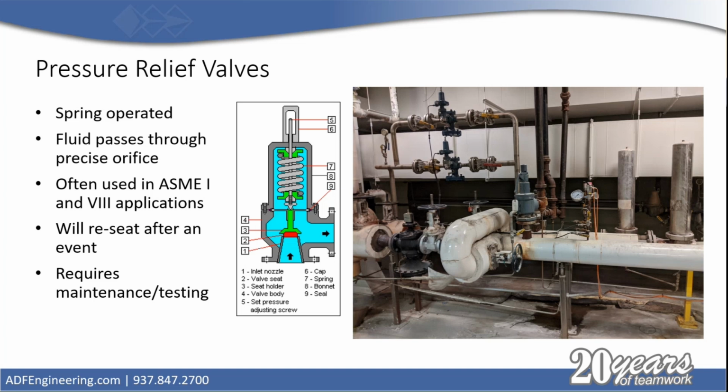So when you're sizing a relief device, you're really sizing that orifice, and that's what's doing the relieving. And the process connection sizes are a result of that orifice. Oftentimes a particular orifice size will have a typical inlet and outlet size, but it's not always the case. And there is some variety in that. So if you're looking for a 3-inch relief valve, what you're actually looking for is the orifice that would maybe be aligned with those typical process connections. So I think that's an important distinction.